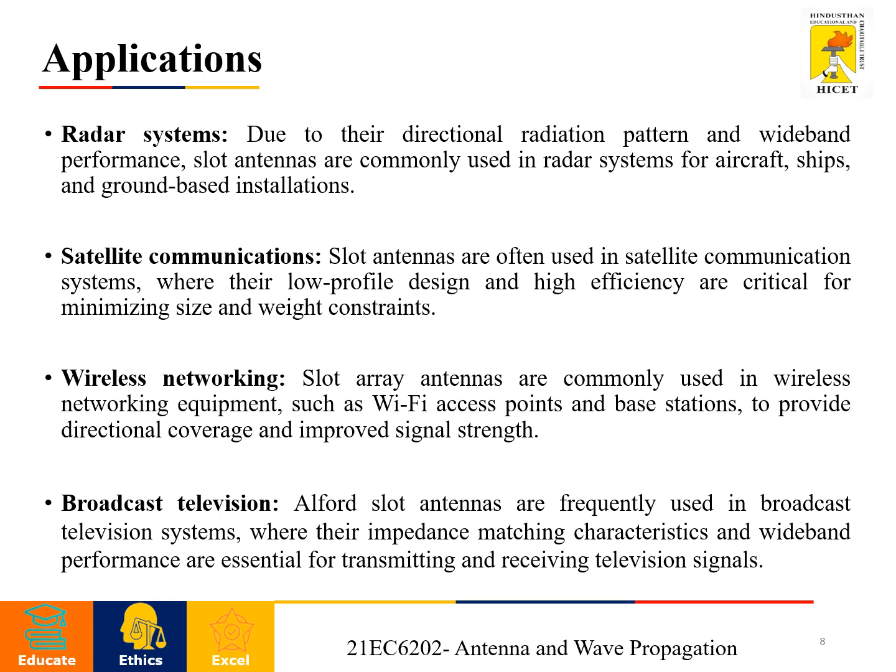The next one is applications of slot antenna. Radar system, first application. Due to their directional radiation pattern and wideband performance, slot antennas are commonly used in radar systems for aircraft, ship and ground-based installations. Next one is satellite communication. Slot antennas are often used in satellite communication systems where their low profile design and high efficiency are critical for minimizing the size and weight constraints.